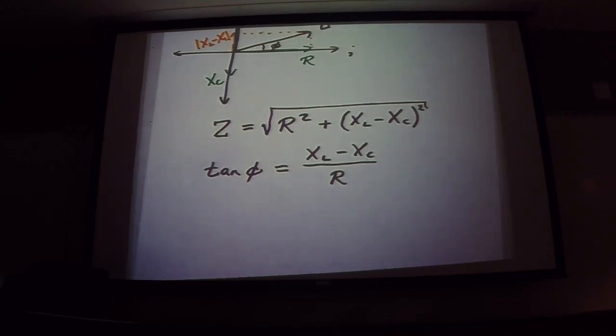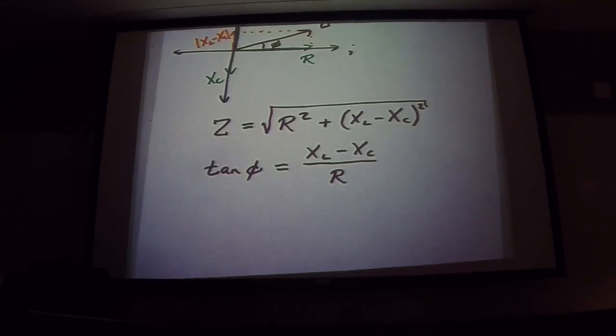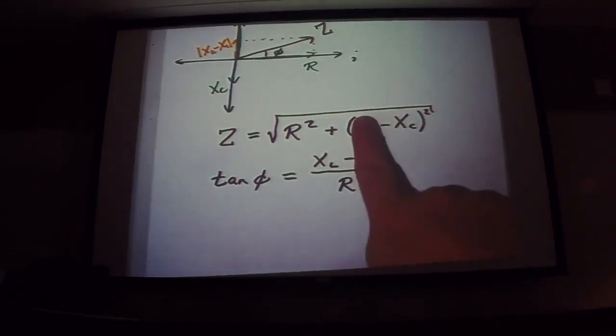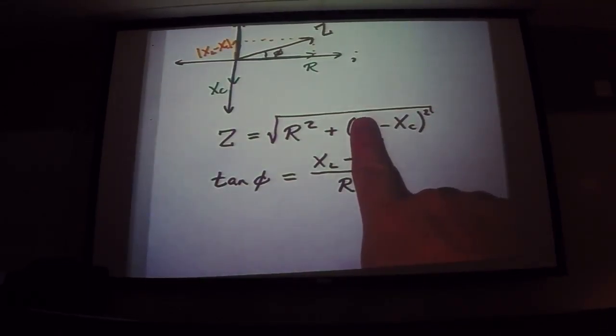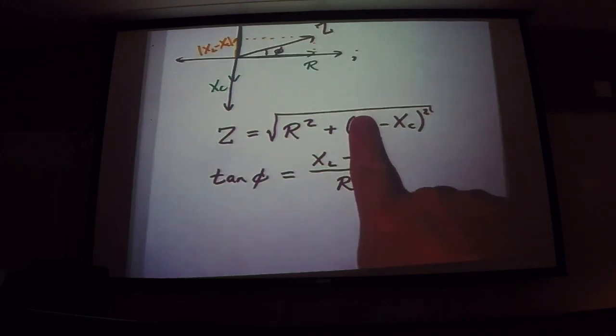I was thinking about if there's no inductor, on the square root, would you keep the minus sign? But it doesn't matter because you have a square. See, what happens is it's negative XC squared. This is where people make algebraic mistakes here. If you have no inductor, the negative sign gets squared.